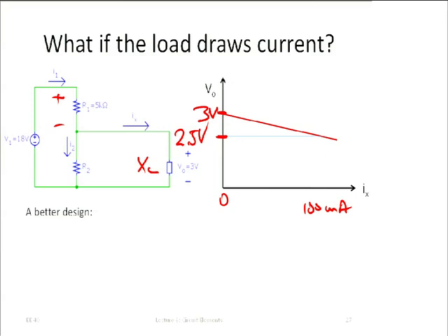And then, as the current gets to its maximum, the voltage coming out of our supply is going to be at its minimum, and the component tolerates a minimum of 2.5 volts. And so that's the characteristic that we're going to design for. Okay? So now we have a more practical goal. We want to build a supply that follows this red line, those characteristics.